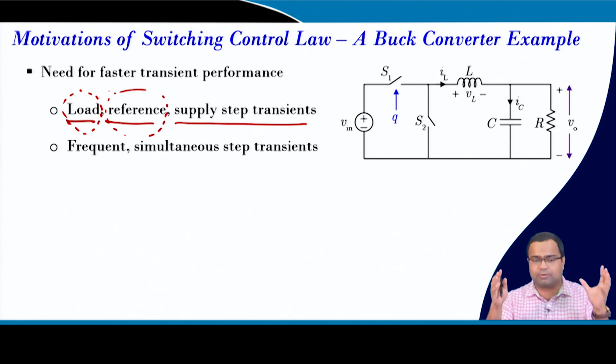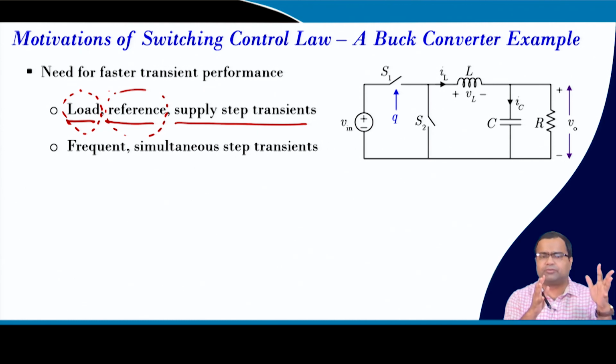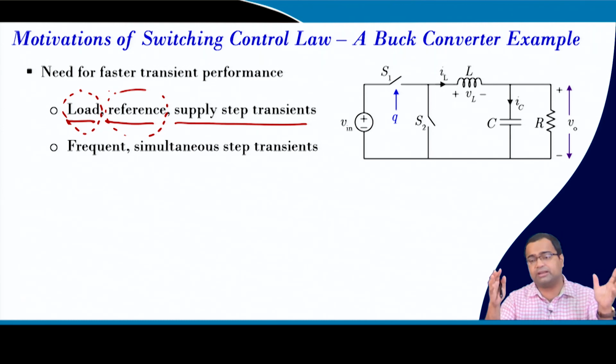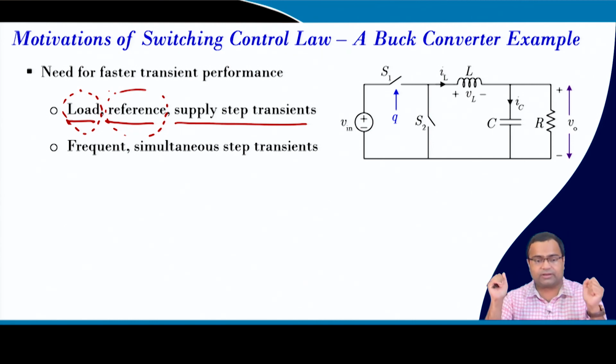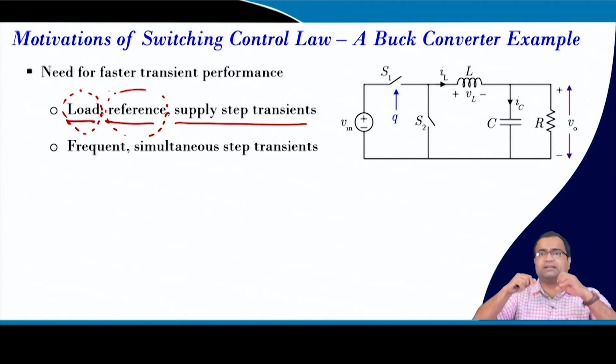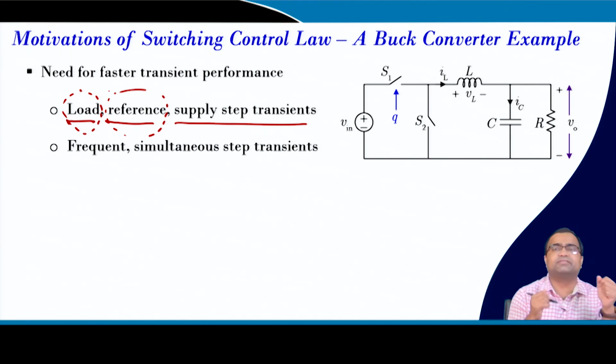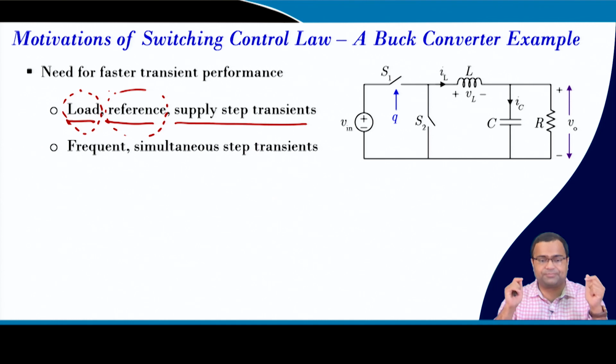If we talk about a cascaded converter, like for a constant power load, for a 48 to 1 volt application, there is an intermediate bus converter, which can be a normal buck converter or an isolated converter, followed by a multi-phase converter. In the first stage converter, when you want to optimize the DC link voltage, you need a reference transient for the first stage converter.